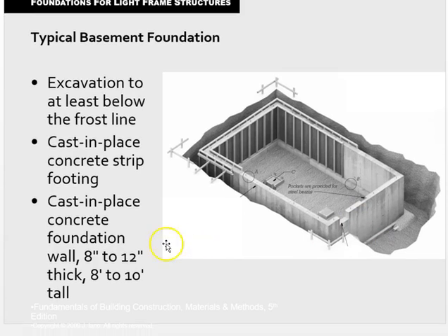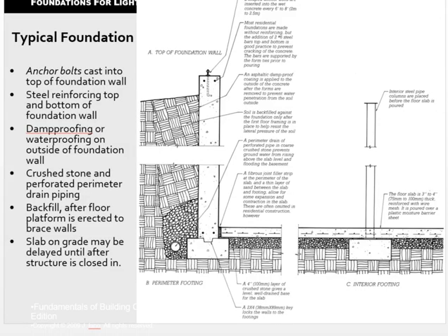Okay, moving on. And now we'll look at some closer details here. So there is the list on the left just runs through the different pieces. I'll run down it quickly. So first we have our anchor bolts here. These are cast into the foundation, and the pressure treated sill for the frame that will be coming above, the platform that will be coming above, would be connected.